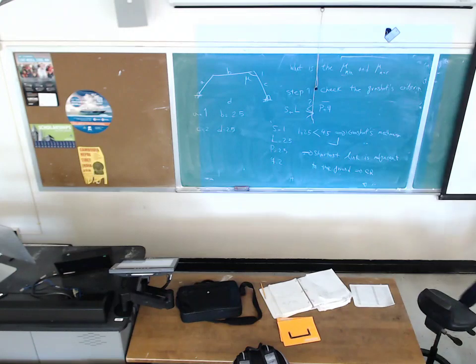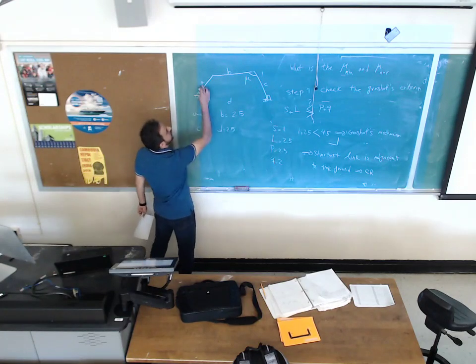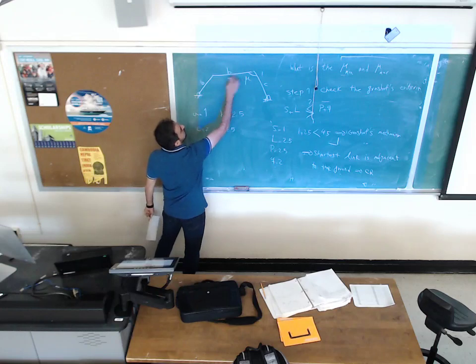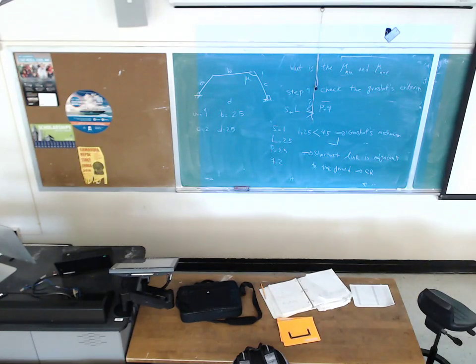We can use this equation to find mu min and mu max. Cosine of mu min, it occurs when theta equals 0, so it's going to be B squared. B is the coupler, no matter how I label the links. In the equation, B is the coupler. If I label this B, still this one should be used for the coupler over there. So be careful about the labeling of the mechanism. In these two examples, they are the same, but if I change the labeling, B is the coupler, C is the output, A is the input, and D is the ground.